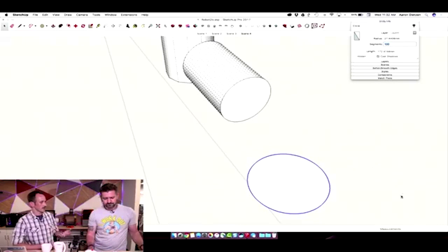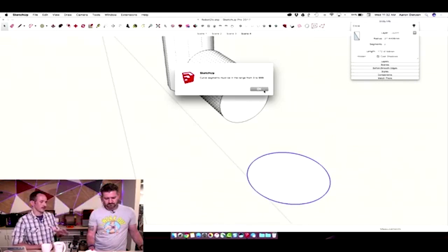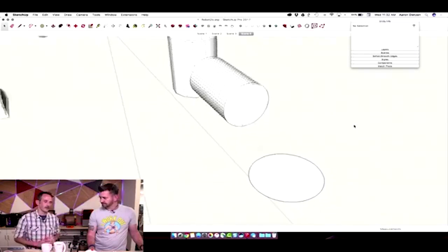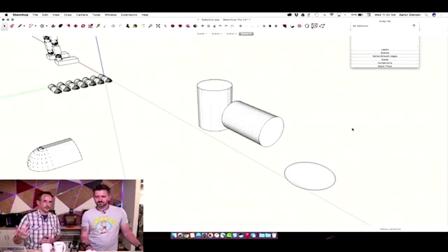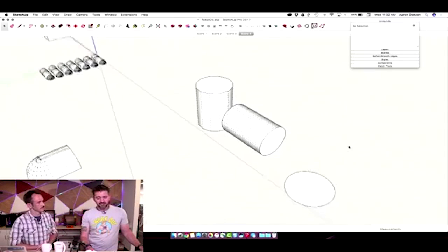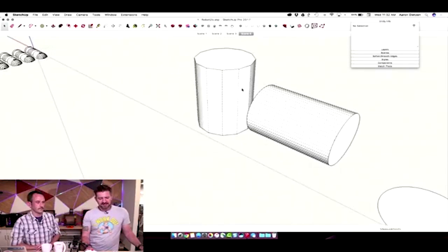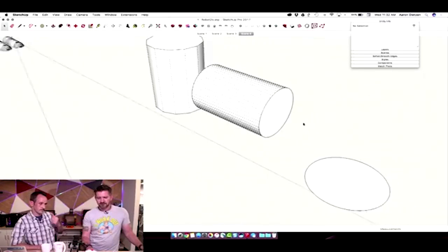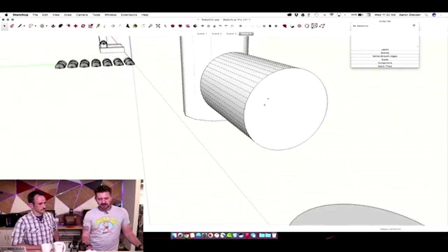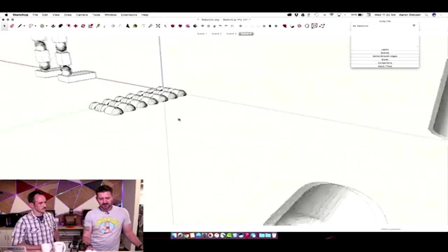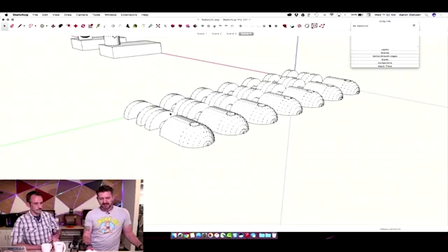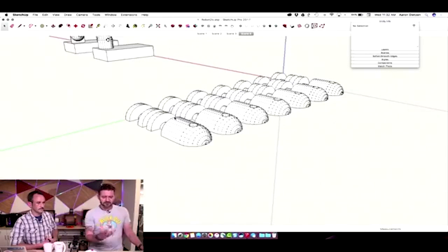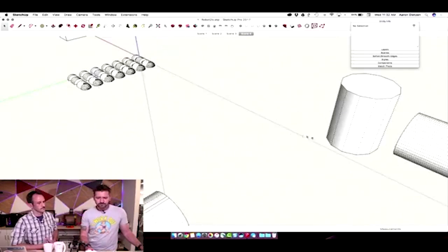And for 3D printing, this is totally okay. This is something that you want to pay attention to, though. If you have a large SketchUp model, the more circles you draw with higher segment counts, the more complex the resulting geometry will be. So keep that in mind. Yeah, absolutely. If you're talking about flat sides on the side, that's just a question of resolution of the circles. If it's an issue with printing circles laid on the side, that's where I went through and split my geometry in half horizontally, because circles printed from the side can build up from the bottom, but it's hard to model from the circle up, basically from the print bed up.